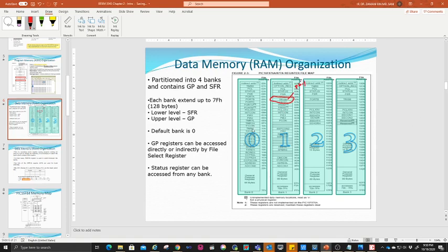Okay. So if you set this 8-bit here, this is bit 0, right? You can only set either 0 or 1 in this register. If you set it as 0, this bit is going to set pin RB0 as output.